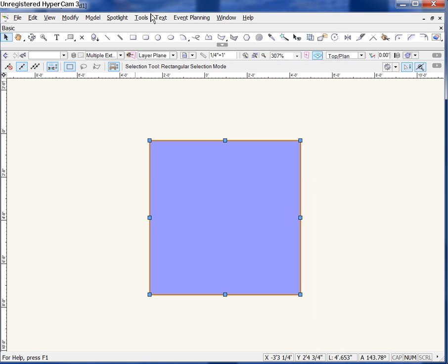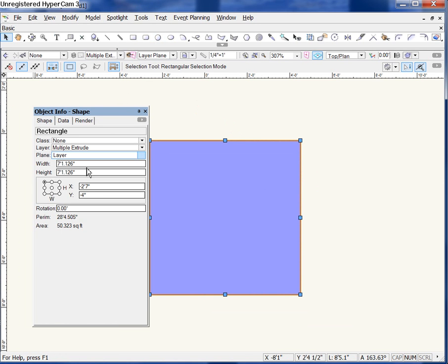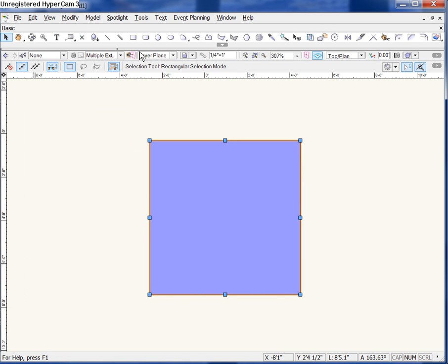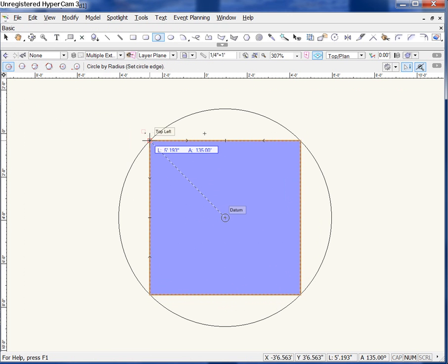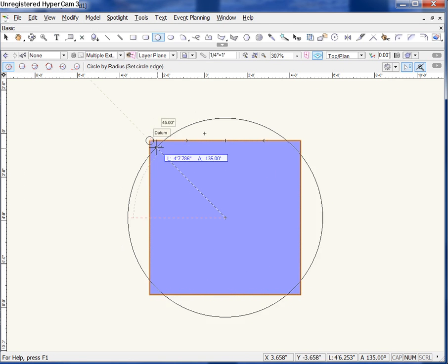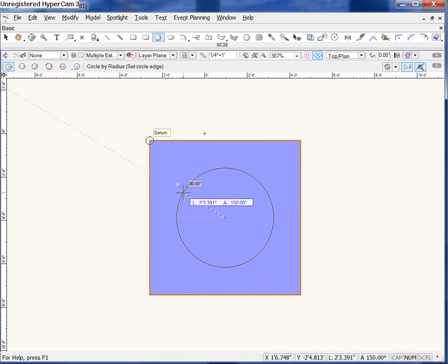You can still create this shape. You just have to be a little more clever about how you align the handle points. Now in your object info, you can notice that we have our little handle selection points. If I grab my circle and pay a little more attention, my first thought was to click and drag toward the upper left-hand corner, where the origin point of my rectangle is. Doing that gets you close, but not quite.